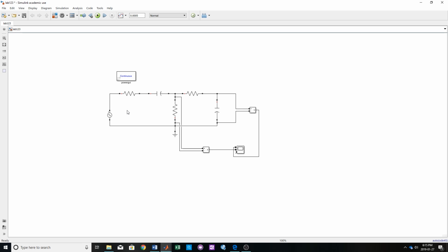So let's say you also want to track the signal coming from the source. So you're just gonna copy one of these again. Just capture your voltage. You can put it over here, let's say, and then you're just gonna put it across your, so from ground to this place right here. This one is from ground to that. Okay, anyways, now we're going to connect this into your oscilloscope.